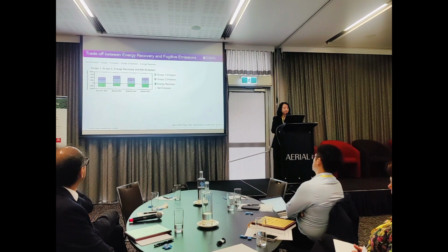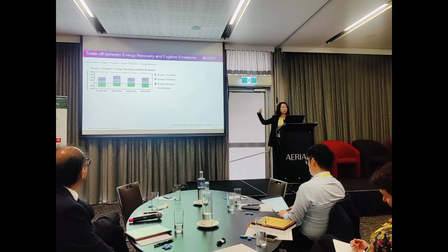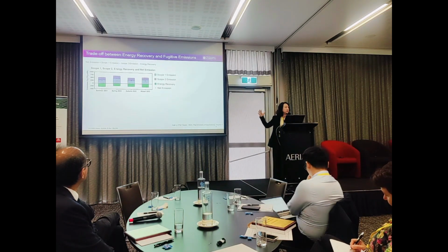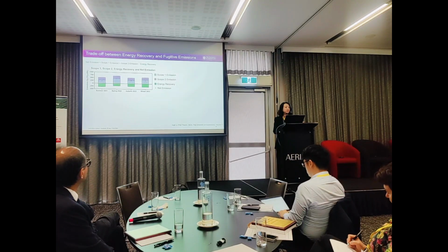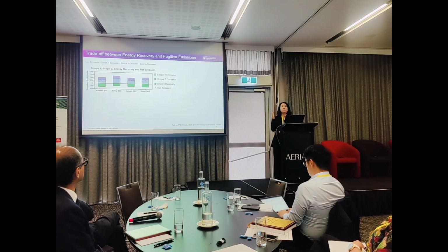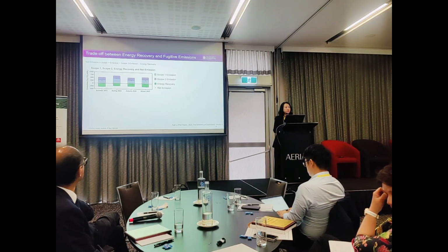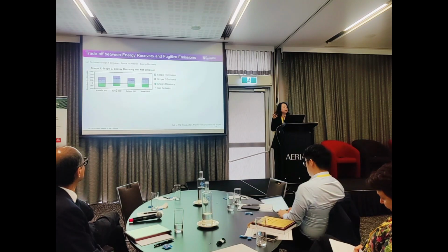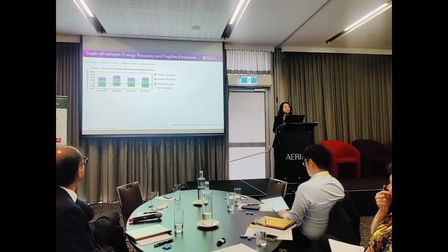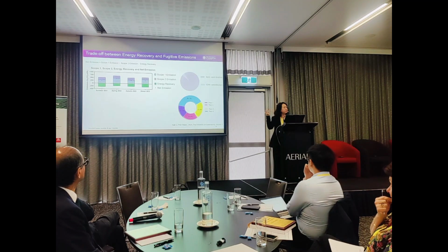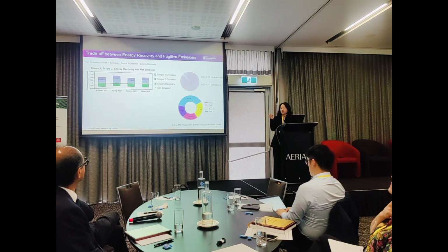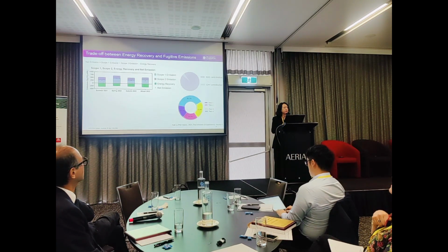So we calculated all the methane captured and used to generate energy, and we also collected all the scope 1 N2O and methane emissions in the following stages, along with the energy used for aeration, which we converted into emissions. The green is the energy recovered from the biogas. You can see it more or less offsets the purple, which is the energy used for aeration, so it roughly offsets all the energy used by the treatment plant. However, the leftover blue is the scope 1 emissions, which is dominant. Some of the methane is stripped out, but it is dominated by nitrous oxide, because we have to multiply N2O by 273 when converting to CO2 equivalent.